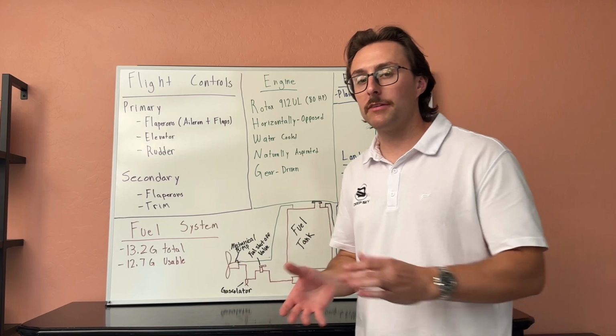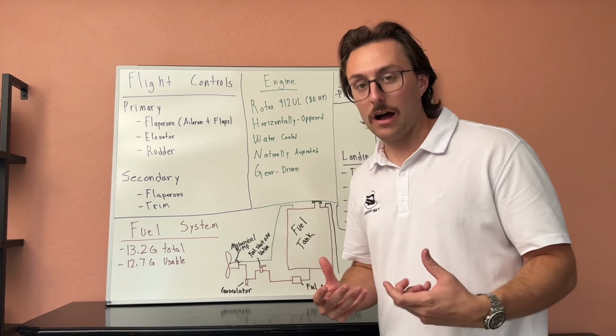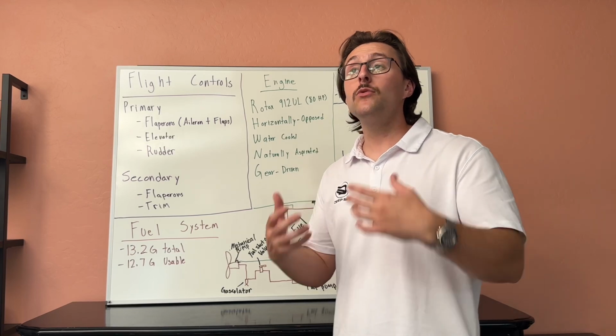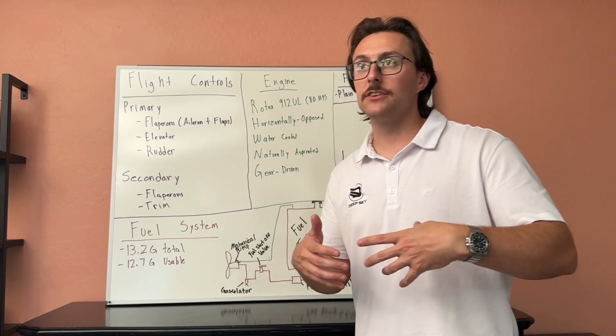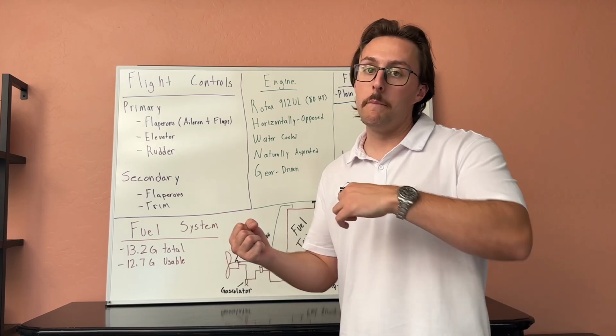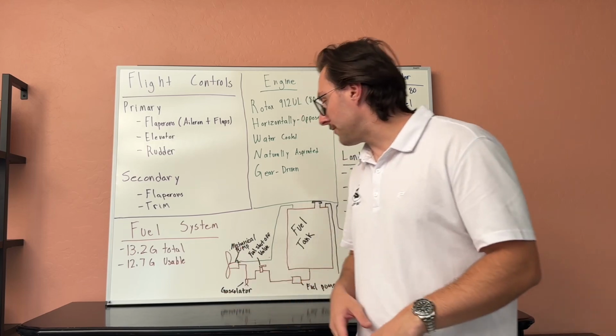Where's that 0.5 coming from? When the FAA completes what's called a run-out test, so you're running until the engine shuts off, it is the fuel that is left in the lines at that point. So it's called unusable fuel because there's not enough fuel to make that fuel usable. The engine's going to shut off before you can use up that fuel.